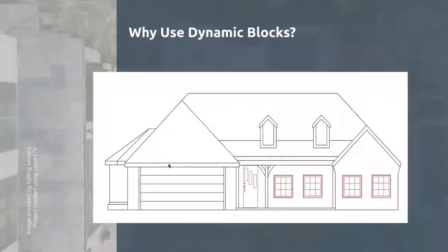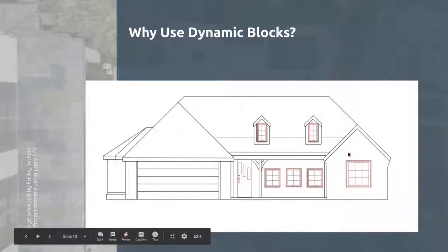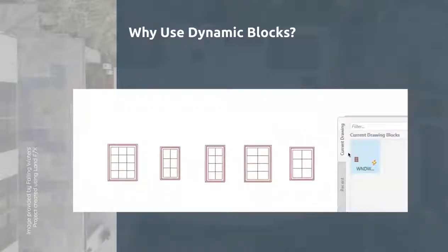And so if we wanted to create windows for this house elevation, we can transform the window to an appropriate size to fit within the house, or we can use the same block copied around and actually change the size of the window to different sizes. So these are all the same block reference, but they have different states that have been activated for this application. And here you can see all these different windows are still referencing a single block within your block dialog box.